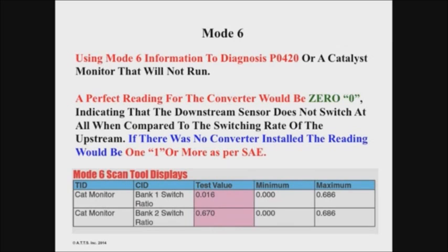And you guys that don't have emission programs, you're worrying about what monitors are, you don't care about them. Monitors are important. A monitor, if it's ready, is going to give you a code. If it's not ready, you've got an issue somewhere, and it's not checking your work real well. So you should always look to see if your monitors are ready. Now, before that pending code, here's where Mode 6 comes in. Mode 6 is not all that hard to understand. It's not new. It's been around for years.